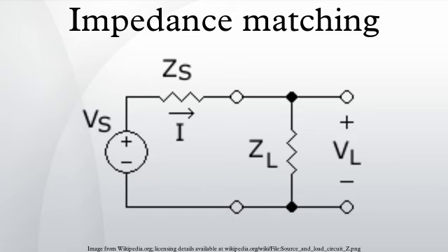In a transmission line, a wave travels from the source along the line. Suppose the wave hits a boundary. Some of the wave is reflected back, while some keeps moving onwards. Let V_i and I_i be the voltage and current that is incident on the boundary from the source side, V_t and I_t be the voltage and current that is transmitted to the load, and V_r and I_r be the voltage and current that is reflected back toward the source.